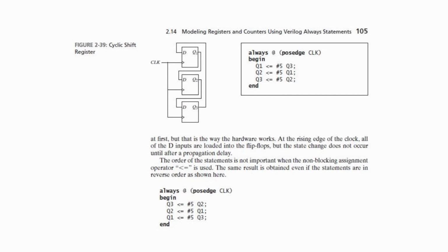And the next part is it needs a triggering pulse or a signal to enable it. So in this case, it's a clock. And as you can see in this program, we are using the positive edge trigger clock. Which means for the positive or high values, when the clock pulse goes from 0 to 1, our flip flops are triggered and turned on. The flip flops are only on when the clock pulse is 1.